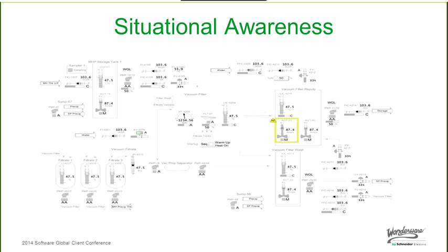This is an example of the situational awareness demo we have at Wonderware. Here we are showing you what we think of the concept. We are limiting the amount of colors that we are using. We have a gray background, and we're moving towards analog meters. The picture itself is very gray and boring, and that's intentional, because the only time we want to introduce bright colors is when we have an alarm, when something is not correct or something is wrong with the process.